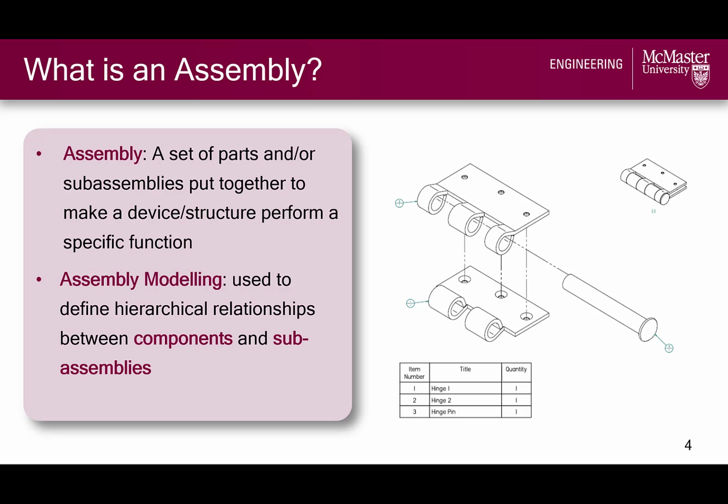So far, we've learned about modeling single parts, but the application of solid modeling on its own is limited since very few devices are made of single parts. Instead, many products consist of multiple components that must be assembled together. This is essentially what assemblies are. Assemblies are a collection of parts or subassemblies that are put together to make a fully functional device. In the context of computer-aided design, assembly modeling is a process of defining the relationships between all of the components and/or subassemblies to arrange them as desired.